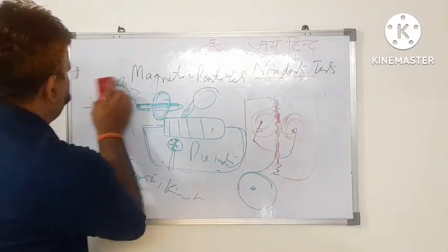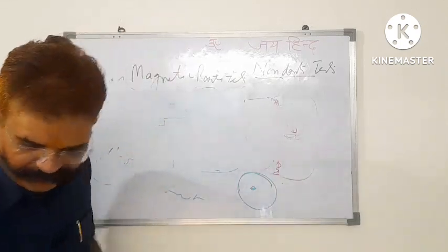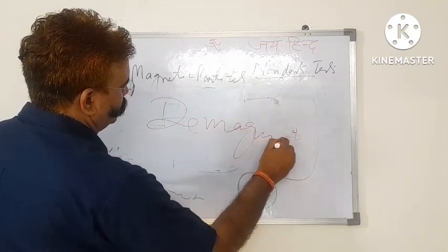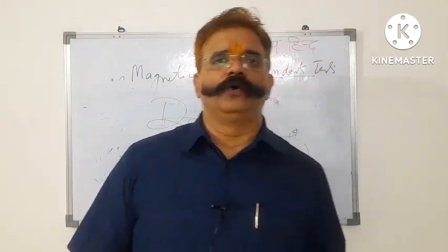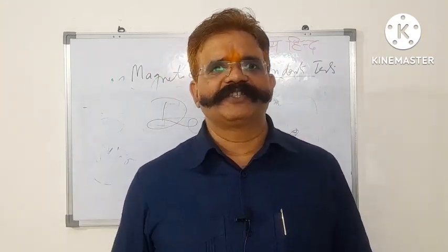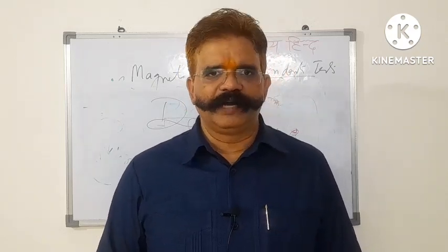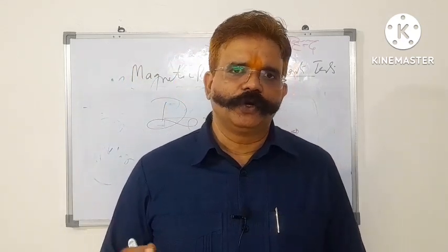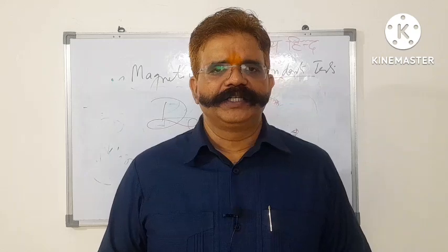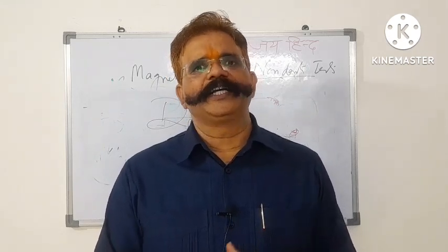Since these components are magnetized during testing, after the test you cannot leave them like this. After that, demagnetization is essential, because you really do not know what is going to happen in the future with this particular component. There might be some other workshop activities in future with this component, some grinding, some sort of other experiment. So if your item is kept magnetized, and another workshop man starts grinding, what will happen? All the iron filings will be attracted to that particular item itself. There will be a problem, the component may get destroyed.